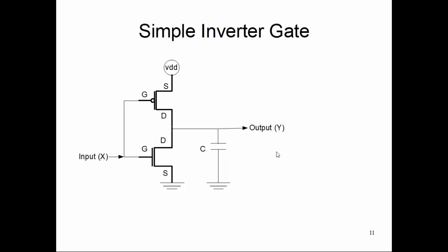So now how does this work? Let's say I am applying a logic 0 on this X. That means the NMOS is off and the PMOS is on. We can imagine a current is established because the PMOS is on, but since the NMOS gate is off, that current won't go to the ground directly. It goes onto this line, and since the current is established, there is a potential difference between this point of the capacitor and that point, so the capacitor gets charged up.